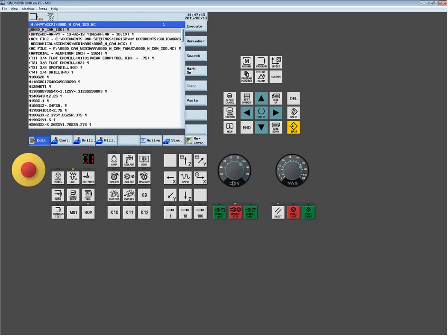Okay, so we go in, now we start to see what the part program would look like. And this is very, very typical. G20, this would be inch mode in the ISO protocol, G17, G40, 49, standard header statements, G80. Tell it to do a tool change. We have a tool change protocol right here for you. We have some other fields like, you know, absolute, setting up our spindle commands.